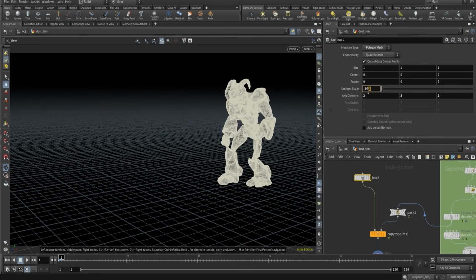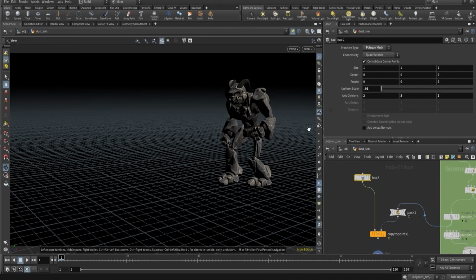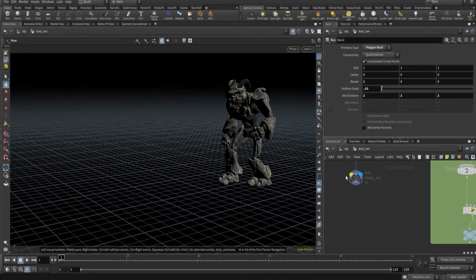As you can see, there is not that much difference, but it will increase the simulation time a lot. So maybe we can just go with 0.005. If 0.005 doesn't give those cool breakups and detailing in the simulation, then the minimum will be like 0.002. Don't go below this value. So that's what we know. Okay, so for rendering we will keep that one, but for a lower-res viewport we can just use this 0.01. Okay, so let's just check.